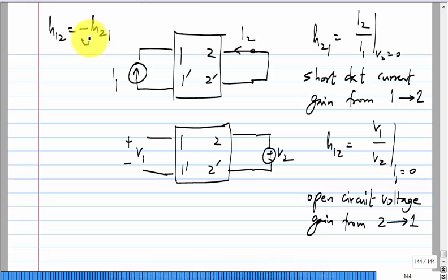In every case, you have two sources and you set the sources to 0, you do not remove it or do anything arbitrary with it. Okay. Or you measure a current gain, you apply a current here and measure the current in this port, that will be the same as the reverse voltage gain. You apply a voltage here and measure the voltage here, except for a reversal of sign. Okay. I mean, all our currents and voltages are denoted by passive sign convention. With that, you will get a negative sign in this one.